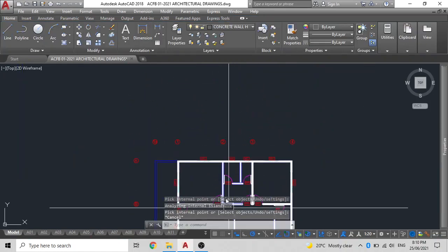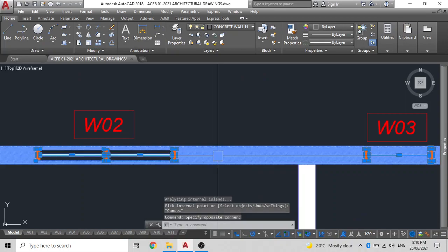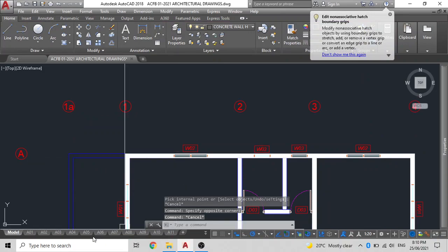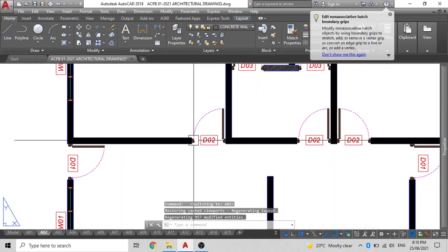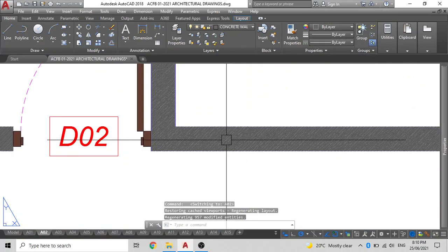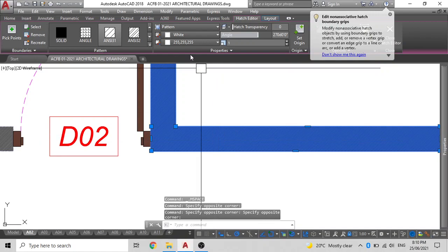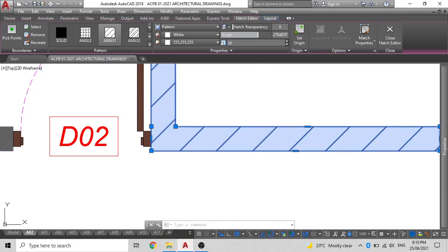If you wish to see what your etch looks like, because one is a white that will print as black, and the other one is just a plain white which will print as white. So what we can do is go to your floor plan that you have set up and locked. If you see that it's too dark, what you can do is double click inside, click your etch, and just change the scale of it. So let's say we can put it at 10. If you're not happy with it, you can put it to 50. And that seems to be perfect for me.